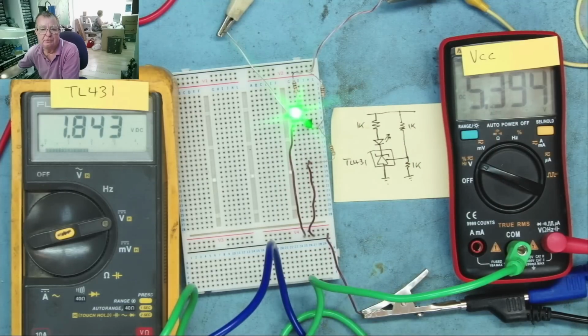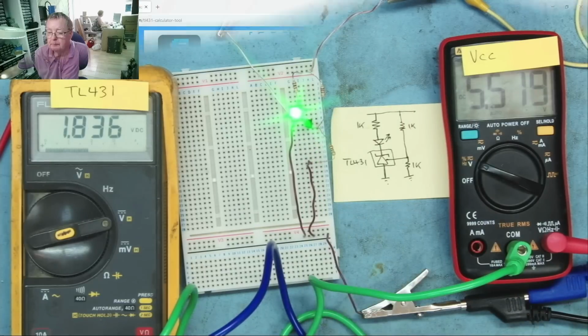You've now reached that voltage and you've now got enough power, if you like. You're driving the transformer hard enough. When that opto-isolator signals back, the pulse width modulator will just back off a little bit, and by doing so it will maintain a voltage which you set using these two resistors.